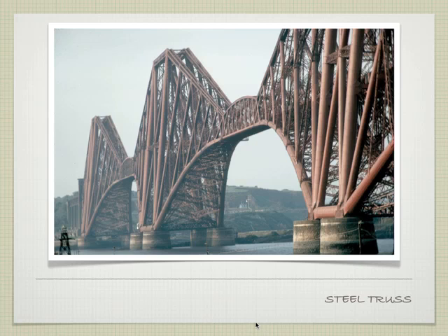So by its nature, it's stronger from a weight standpoint for what it can hold, right? The problem is it itself weighs so much more that you need more structure to support it. So it ends up being less practical, and it's certainly used in some cases, but it's less practical than, say, a truss, right? And so if we're getting up to a large scale like this, this is not something that you want to do with plate girders. It's just too big, right?